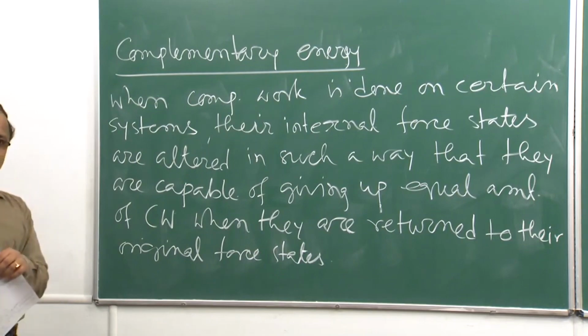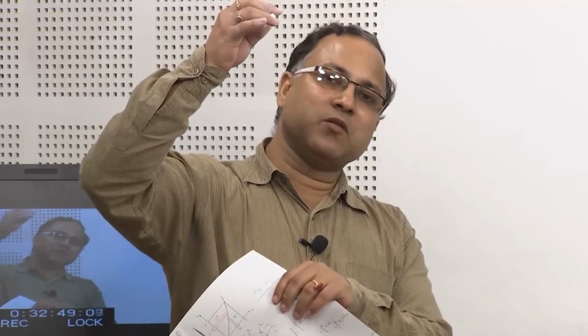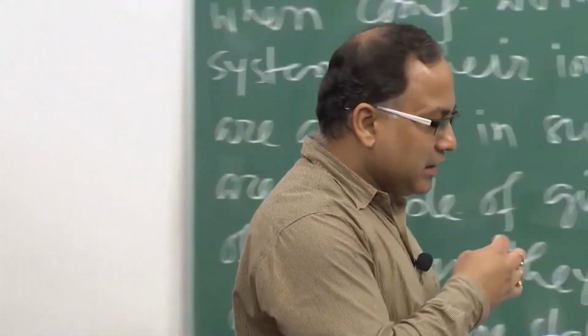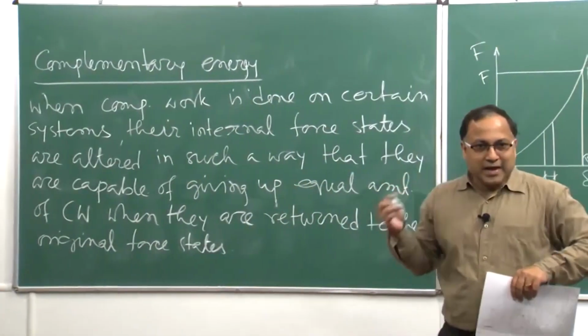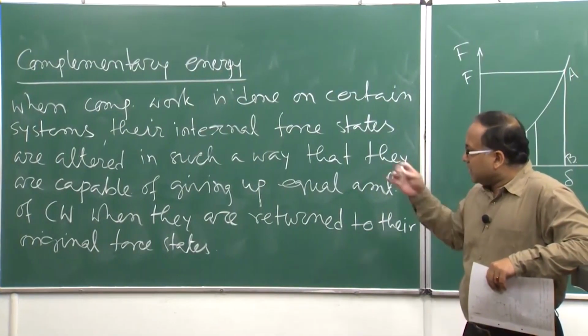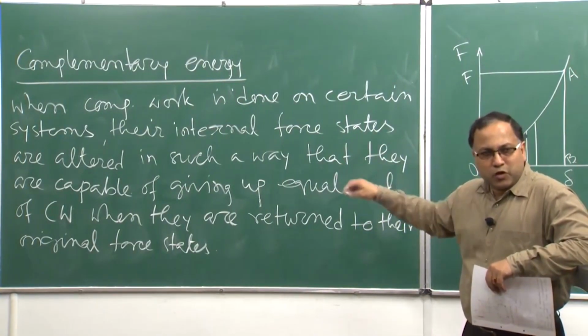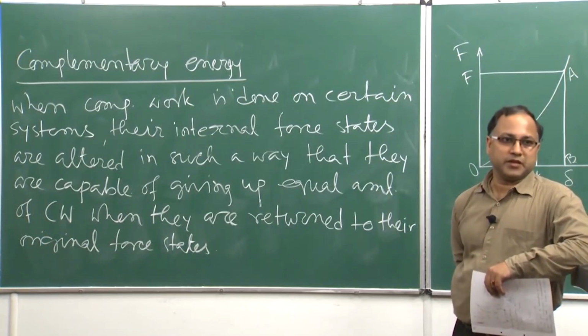That means, you are applying the force, variable force gradually, your system is doing some complementary work. Now, once you remove that force, the system will give the same amount of complementary work that has been done by that force when it was applied, right. So, the energy thus stored in this kind of process is known as complementary energy.